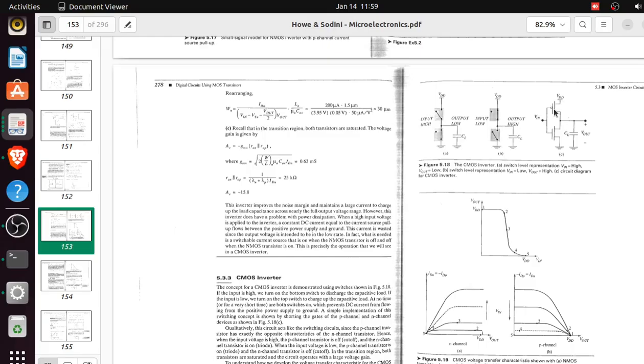It may be a NAND gate, NOR gate, AND gate, or anything else that is also designed with CMOS. It may have to go through the gate of a MOSFET, and at the gate of the MOSFET you basically have a capacitor, right? Just between the gate and the source, you have a capacitor. That's one of the intrinsic capacitances, I think the oxide capacitance.